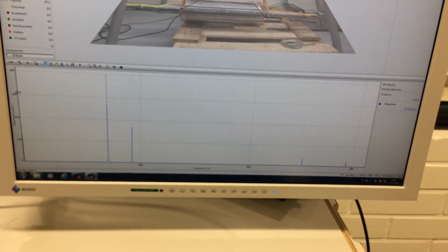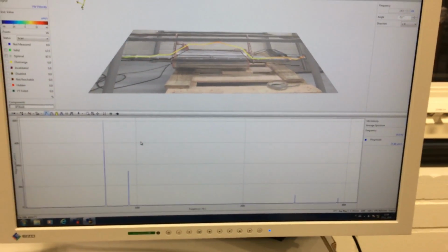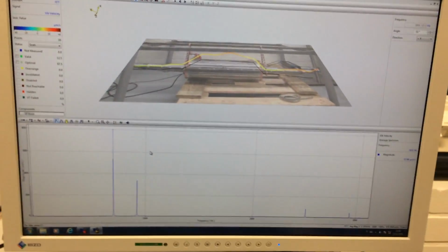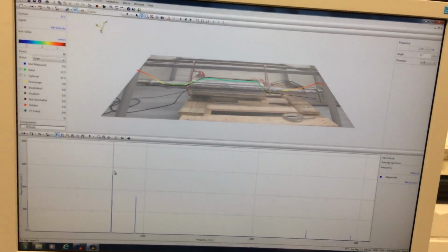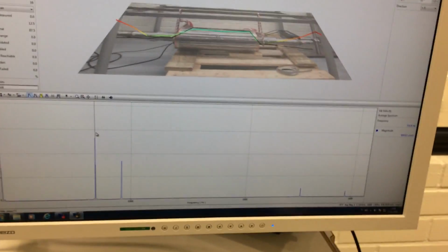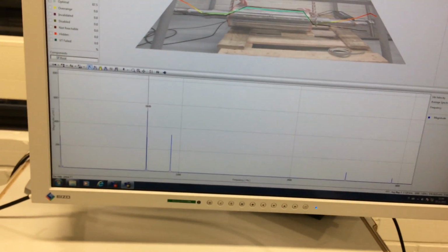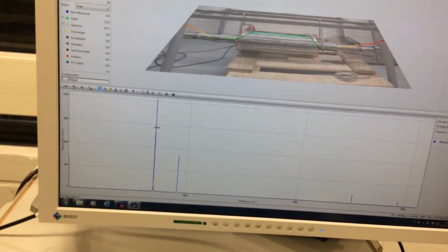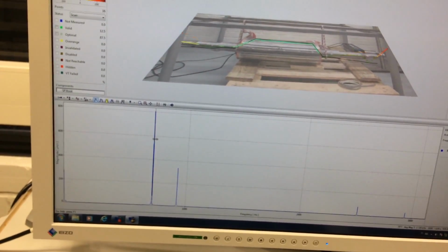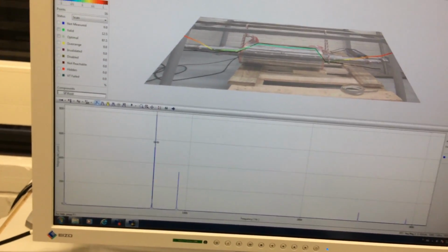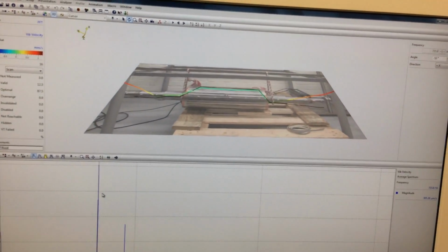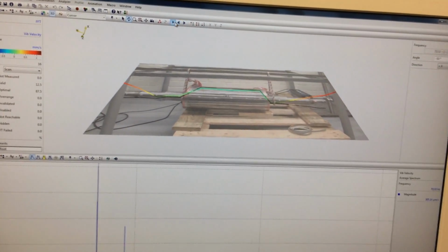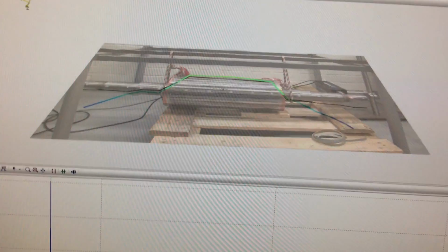So I just go here, don't care for a while. But you remember also for one single point, the detected frequency was about 700. Now still we are in a 700 range. But how can we be sure that this is the first frequency? The place where we can be sure that this is the first frequency is the mode shape.